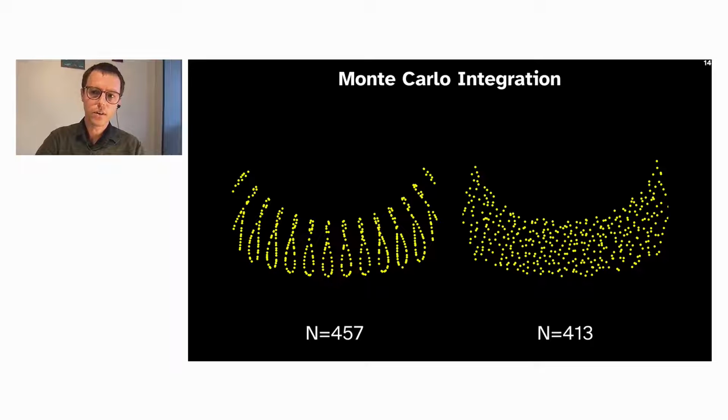Of course, if we are using hourly weather data for the sky conditions and approximating sun positions, these 2 million conditions don't actually contain additional information. They just ensure that the distribution of source positions is more representative of the actual solar transit. Borrowing from the principles of Monte Carlo integration fundamental to the underlying rendering algorithms we use, adding some randomness to the way we select the precise time steps to evaluate will be just as effective.